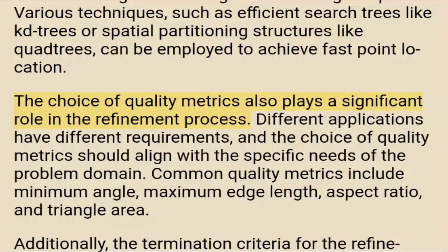The choice of quality metrics also plays a significant role in the refinement process. Different applications have different requirements, and the choice of quality metrics should align with the specific needs of the problem domain. Common quality metrics include minimum angle, maximum edge length, aspect ratio, and triangle area.